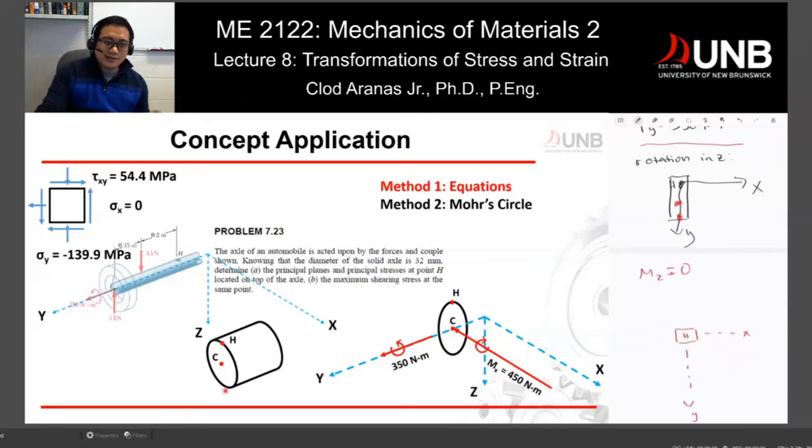So it's pulling an element from the lower side of your axle, pulling it and pushing it going into your H, which means if we look at point H, it's pulling here and pushing it right there. It's producing a compression along y-axis, correct? Now, if we change the moment direction, of course, that would be a different story.